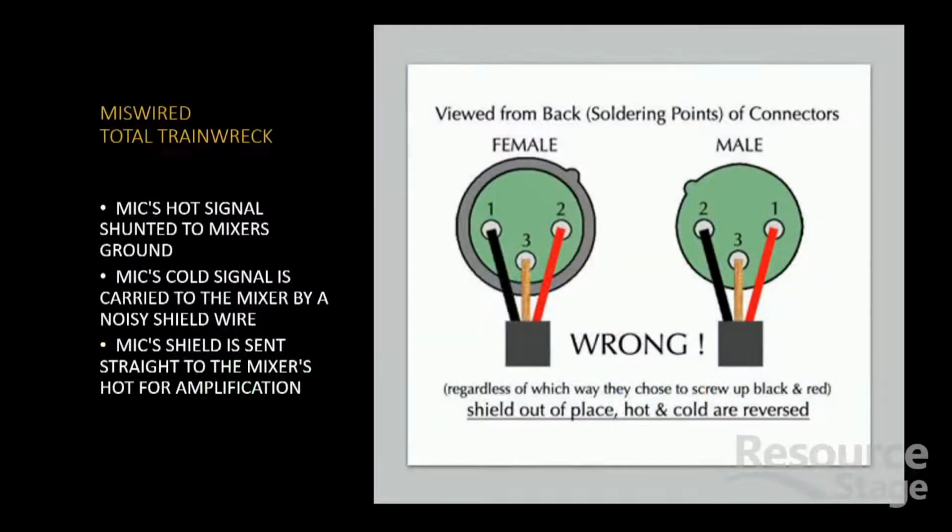This one here, as I said, is a total train wreck. They've got the shield on pin 3, and pins 1 and 2 are reversed in polarity to each other. It's just going to cause all sorts of problems. And so that's what you shouldn't do.